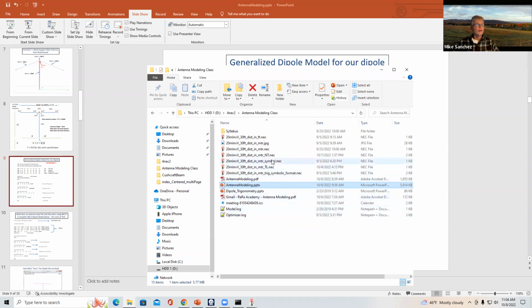If you're working in Notepad, it's going to save it out as a .txt. If you double click that, fornec2 will not automatically recognize it. But if you change the end to .nec, or if you just file open and reach it with a .txt, it'll load just fine. Good question.